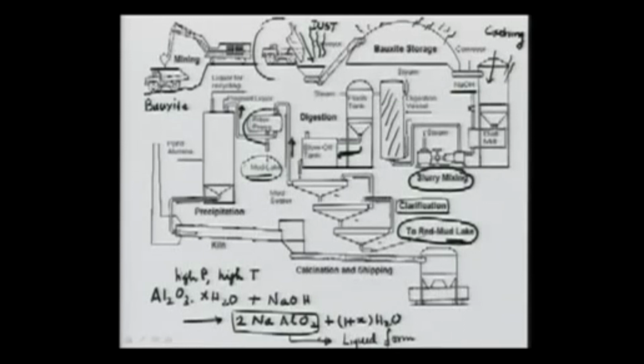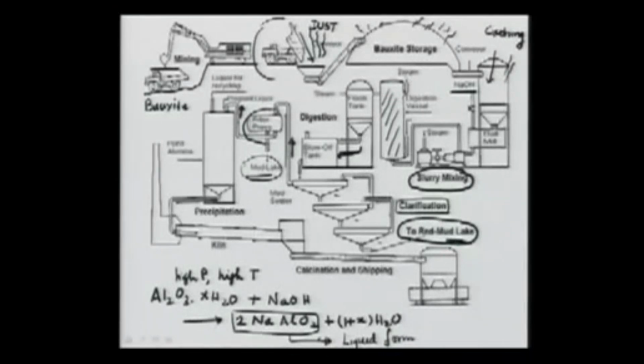Well, from here, after the filter press, as you can see, let me make this arrow here, we take this one to the precipitator. Now after this point, after all the impurities are removed, I have very crystal clear liquid, which is largely sodium aluminate, or again I repeat, NaAlO2. But the idea is not to stop at NaAlO2, our objective is to form Al2O3.